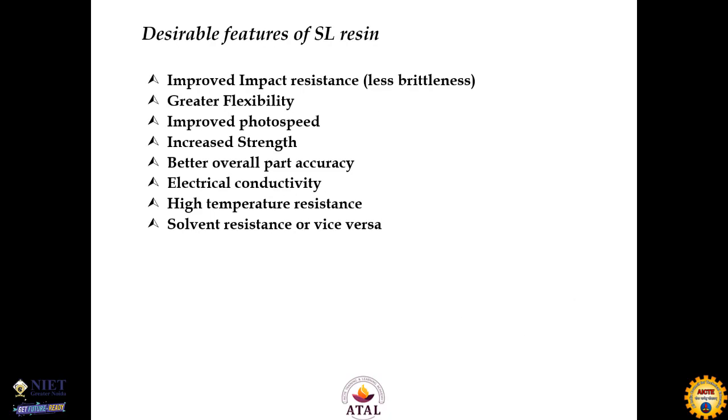The desirable features for a stereolithographic resin are improved impact resistance, less brittleness, greater flexibility, improved photo speed, increased strength, better overall accuracy, electrical conductivity, high temperature resistance, and solvent resistance, or vice versa.